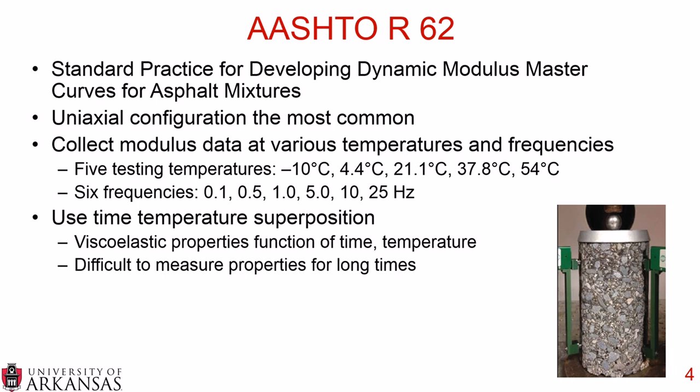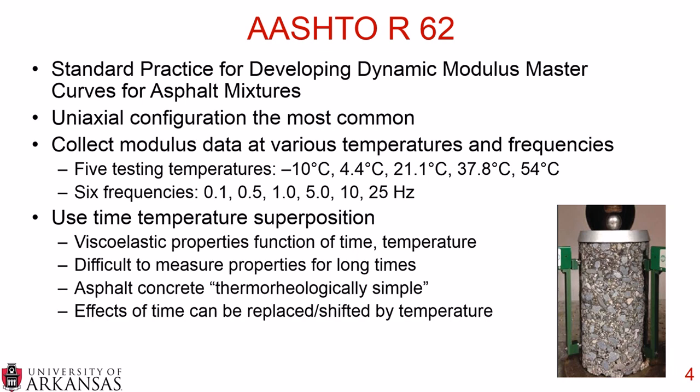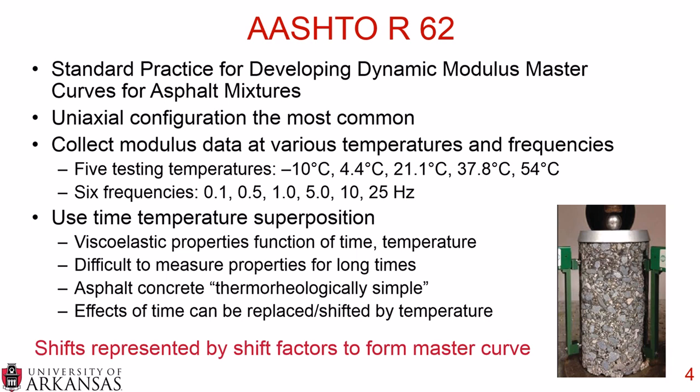And in order to construct this master curve, we use the concept of time-temperature superposition. So this concept of time-temperature superposition is very important. And that is because viscoelastic properties, and asphalt concrete is viscoelastic, are a function of both time and temperature. And as I mentioned, it's difficult to measure properties for either very long times or very short times. But luckily, asphalt concrete is thermorheologically simple, and that means that the effects of time can be replaced or shifted by temperature. And these shifts are represented by shift factors to form a master curve.